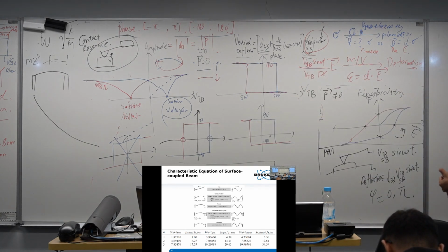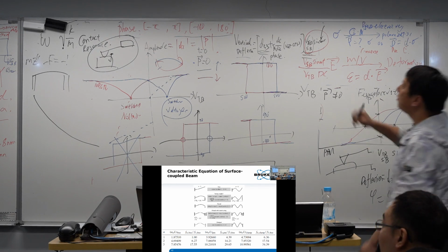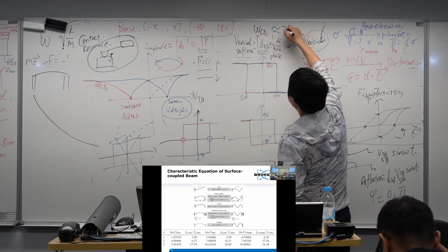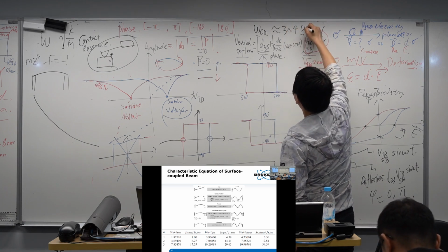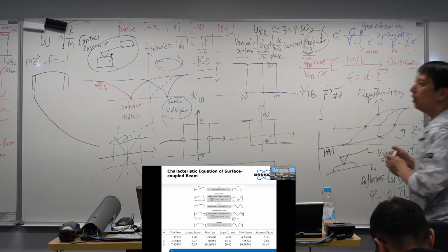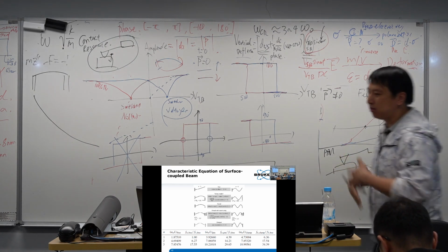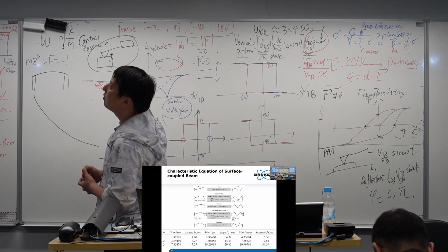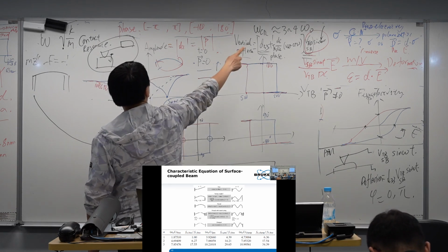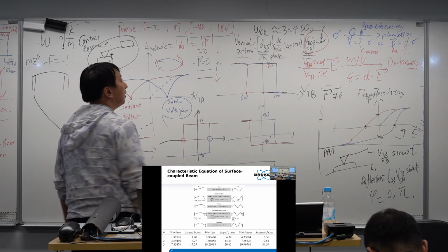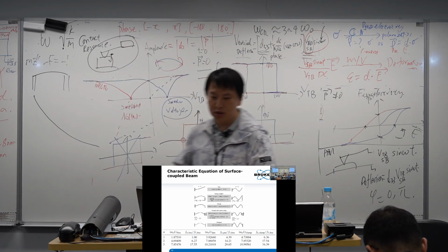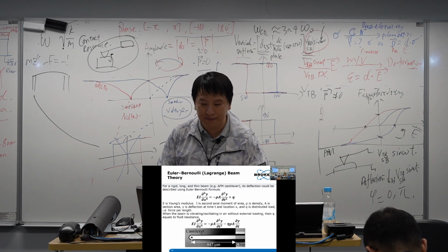And usually the contact resonance frequency is about 3 to 4 times omega 0. So if you find your sample is weak, the piezoelectricity is so weak, you can consider using the contact resonance frequencies, and we will show you how to find it.